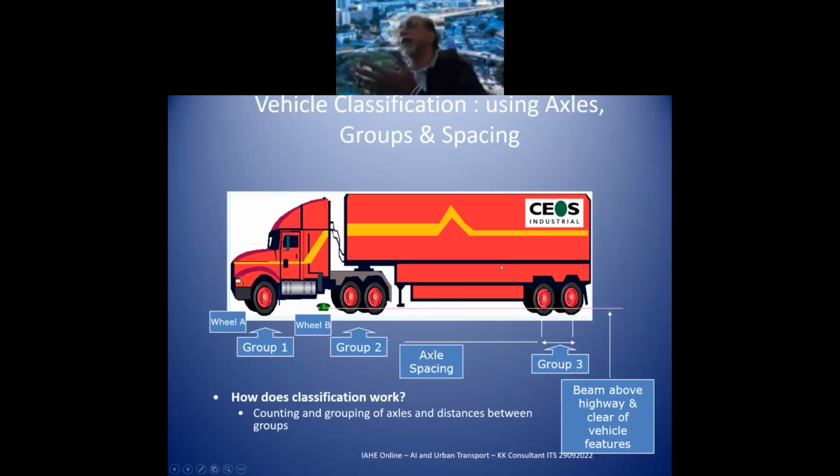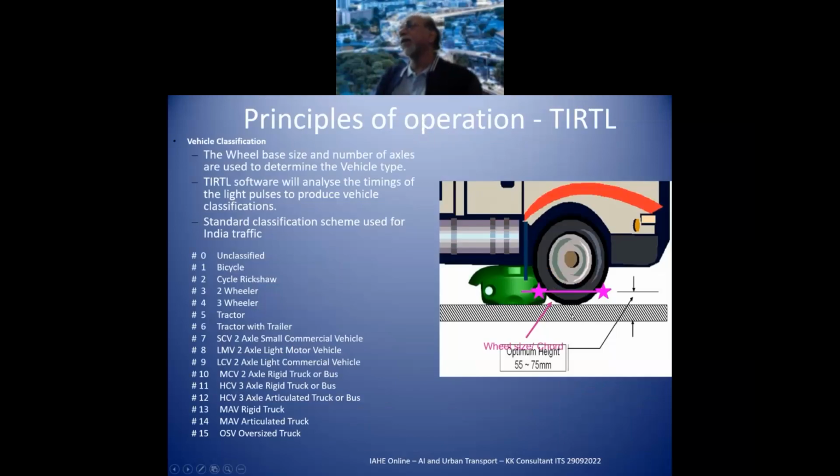Now imagine how vehicle classification is done. Suppose this is a 5-axle articulated vehicle. We will say that when you see a vehicle going in this, it is group one, and in this, 2 vehicles nearby, and then a vehicle, and we also specify the speed and distances between them. Believe me, the system can actually measure them with micrometer accuracy. Based on this data, we are able to classify the vehicles axle-wise. And you can even measure the size of the tire used.